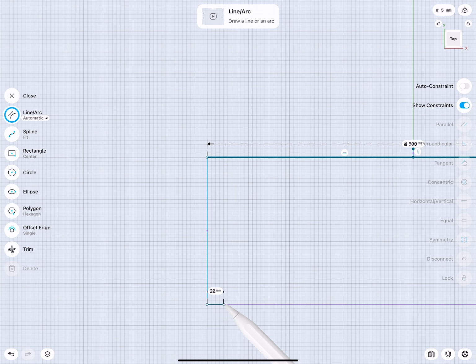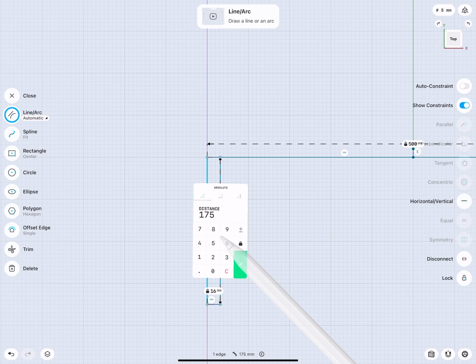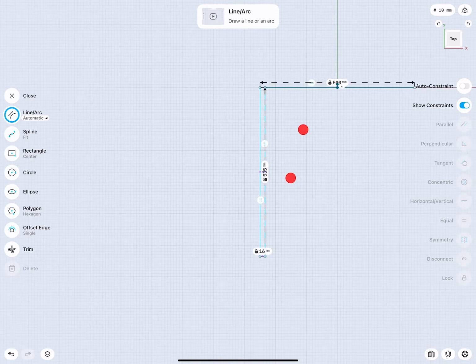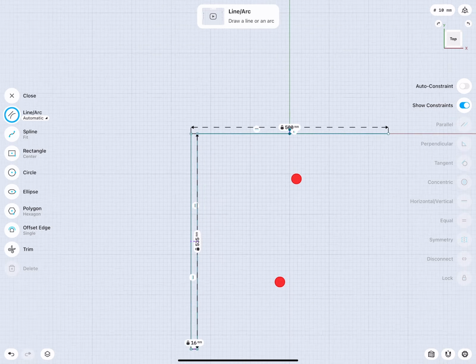Then here I draw a line down, draw a line horizontal, draw a line up, select all three lines, horizontal, vertical. Very good. This should be 16 millimeters. And then this, that's basically the cabinet depth, 535. Very nice. Cool. I'm not going to draw everything on the right side because I will later mirror the body actually over.